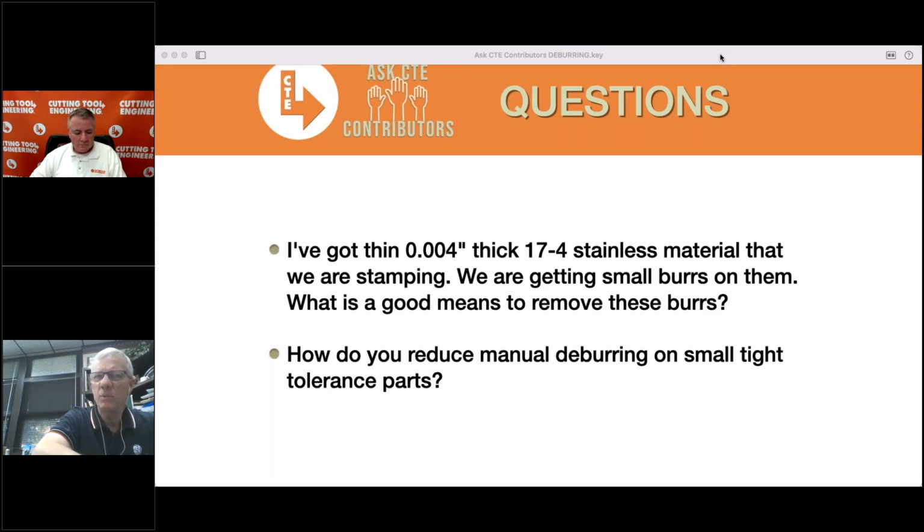So many times while the machine is performing the machining operation, the easiest and best way to do the deburring is in the machine, even though it's going to cost you more to do it. But consider the risk of damaging the part, in terms of a real close tolerance application. So many people will come back with an extra tool while it's still being held in the operation and perform a deburring operation on the actual machine tool itself.